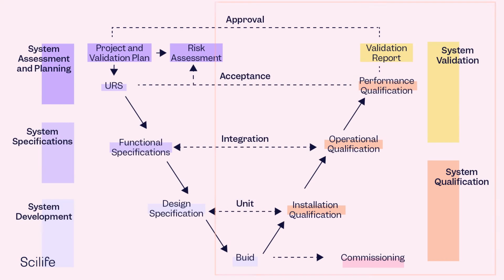Once an equipment or system is built and installed on a site, the next step is the qualification phase. This phase consists of three parts: installation qualification, IQ, operational qualification, OQ, and performance qualification, PQ. Compliance to all three phases improves the overall knowledge of the equipment, process, or system and assures that the process has been well developed, well maintained, and operates as it should. It reduces the risks involved and expenses of routine processes.